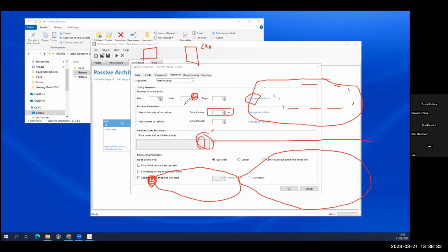Let's say we don't want the cables to be too thick. Then we would like to have a few locations of S1 splitter. So we run with thinner cables. The feeder cable is not so thick, right? If I have a few locations of S1, I need to have a feeder cable going through all of them.